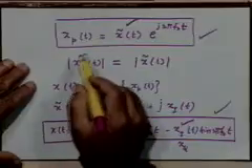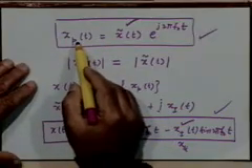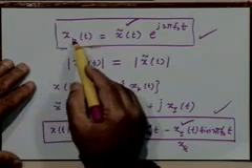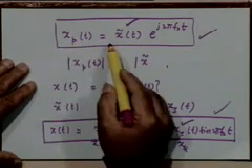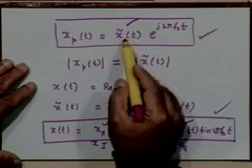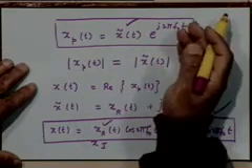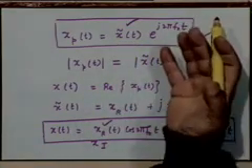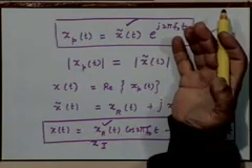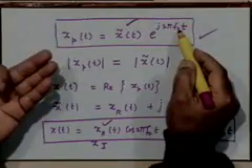For example, the information bearing part of x_p(t) is in fact in x tilde(t). The other part just happens to be the center frequency, an exponential corresponding to the center frequency. It has no particular information bearing aspect; it's a carrier. I could as well change this to f1 or f2 or f3.